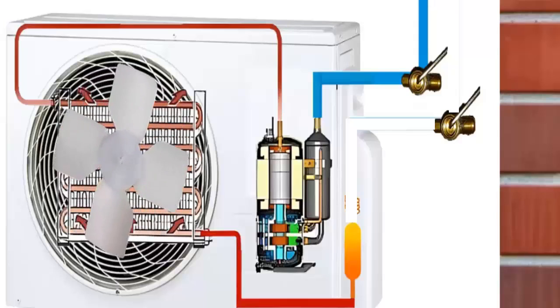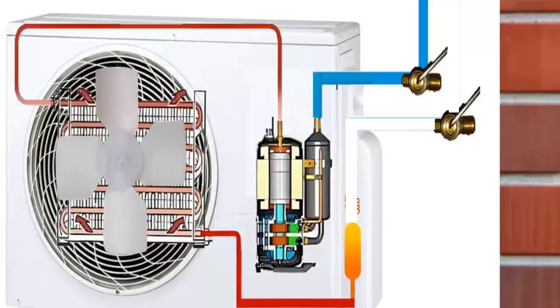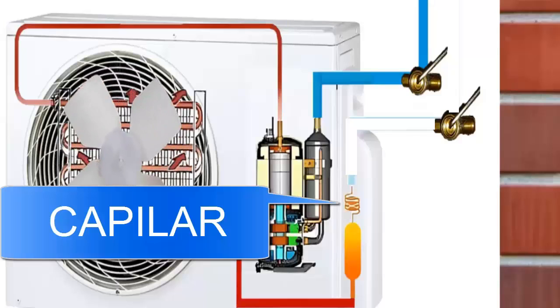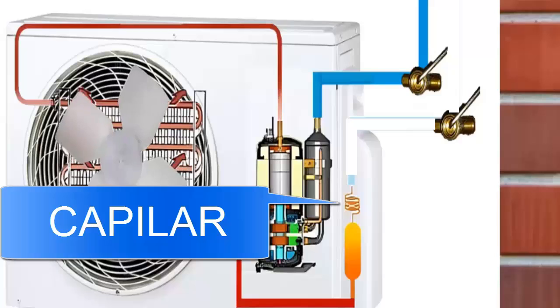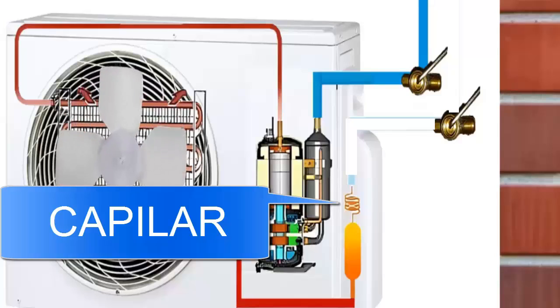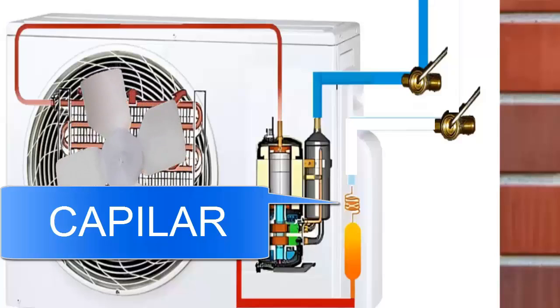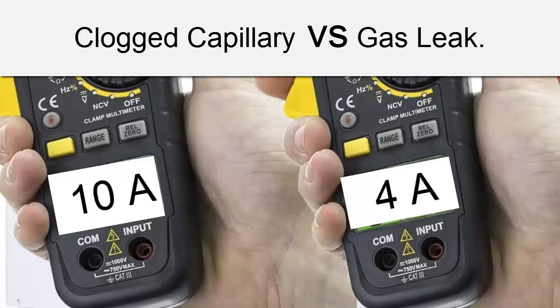6. Over time, when the equipment is turned on, the obstruction in the capillary tube causes a gradual reduction in current consumption, but not immediate. This is because the compressor gradually stops compressing refrigerant, as the obstruction holds it in the condensing unit.